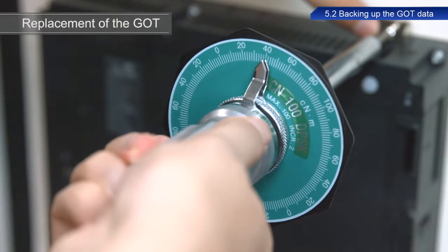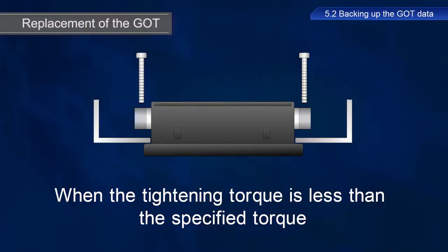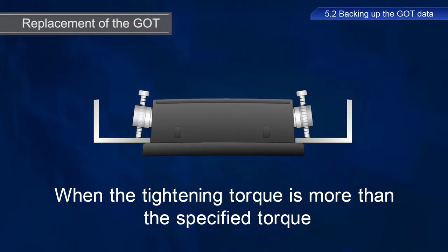Use a torque driver to tighten the screws to a tightening torque within a range of 0.36 to 0.48 Newton meters. If the tightening torque is less than the specified torque, the packing will not form a proper seal and allow water and dust to contaminate the device. Conversely, using too much tightening torque could result in operation failure due to panel deformation or damage, or cause some other failure.